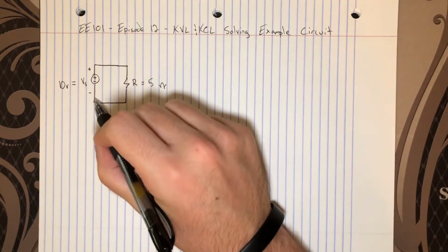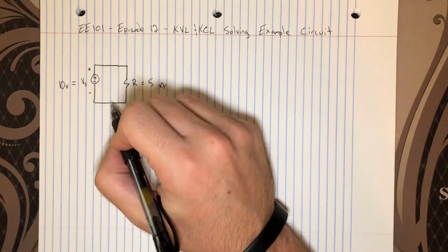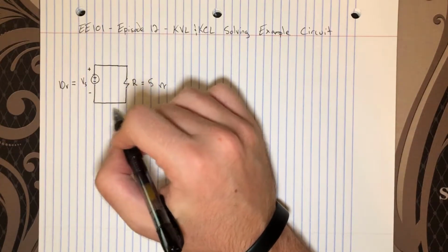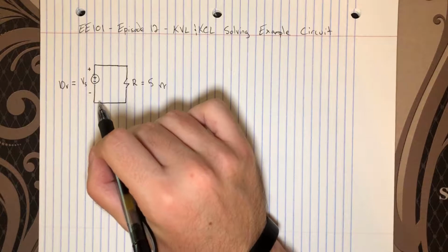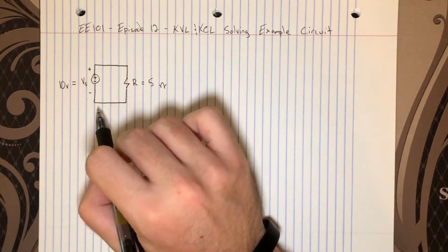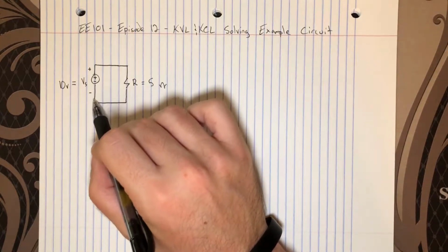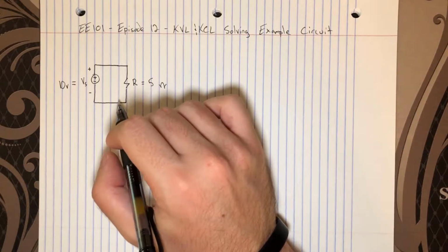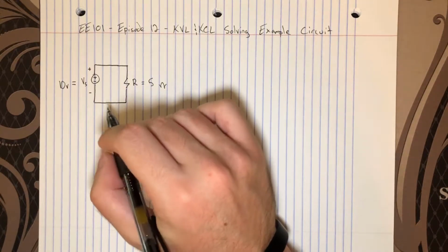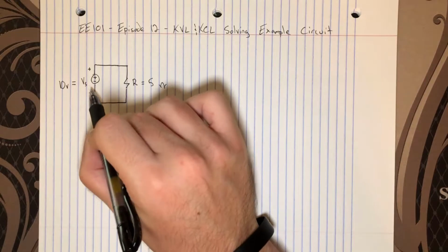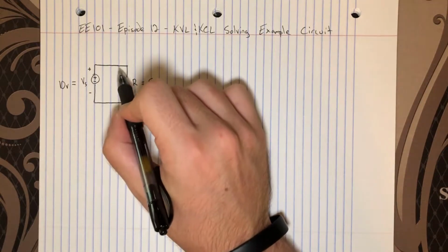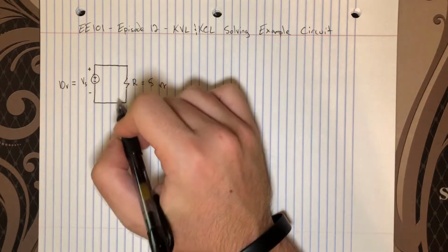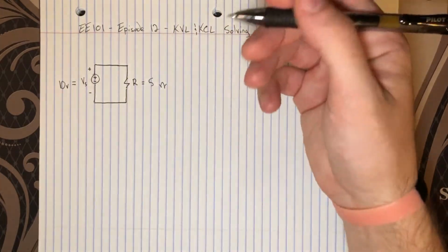The first is the fact that both sides of each circuit element are connected by ideal conductors. And if you remember, that means that there's no voltage across an ideal conductor, which means that any 2 points connected by an ideal conductor share the same voltage at that node. Meaning that I could equivalently just draw this plus and minus Vs, or 10 volts, directly across the resistor R. And that's valid. That's one way to look at it.